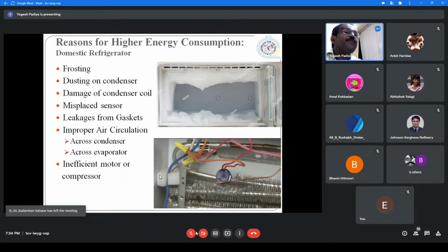Right. Now let us see. Sometimes our freezer could be like this. It means you can find ice being formed on the freezer. Once the ice is formed, the heat transfer from the media to the gas will reduce because this is acting as an insulator. So inside temperature will reduce further, and then heat will transfer. It means now my compressor has to do extra work from that temperature to condenser pressure. So this has to be removed periodically. That is called what? Defrosting.